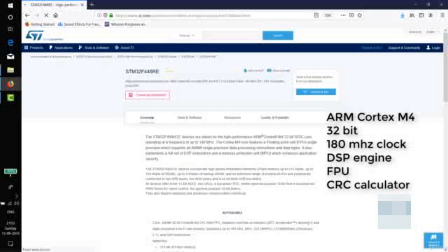The controller with these specifications is good enough to run the complex math functions inside the neural network library generated via the X-Cube-AI extension present in STM32Cube, as we discussed in the previous lecture. With this, we will use I2C pins of the controller to interface to our accelerometer module and UART pins to communicate to our PC.